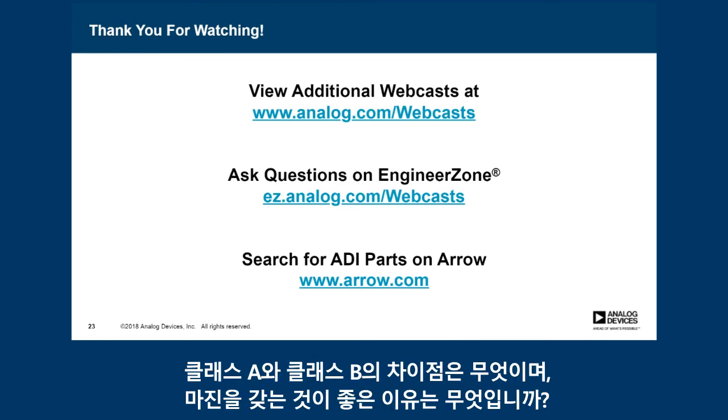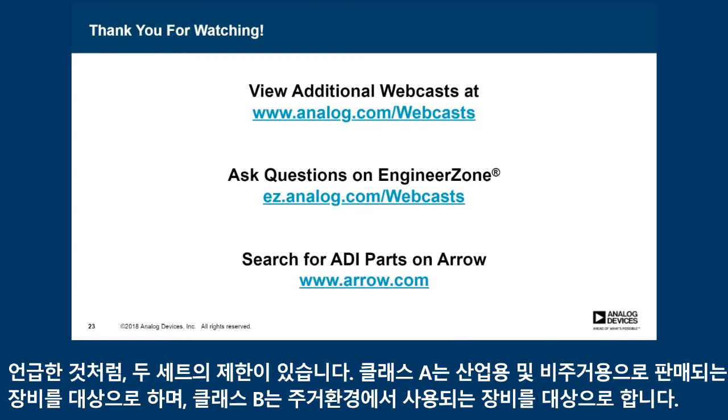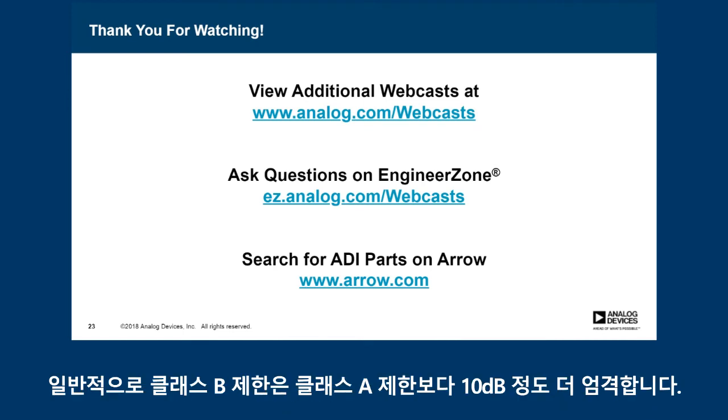David, what is the difference between Class A and Class B, and why is it good to have a margin? Well, thanks, Chris. That's a good question. Within the various CISPR and EN 55022 type specifications, there are two sets of limits, as we've talked about. Class A is for equipment that's marketed for use in industrial and non-residential areas, whereas Class B is for equipment that's going to be used in residential environments. Class B limits are 10 dB more severe than Class A limits generally.